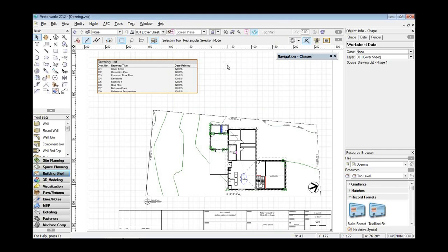That's why it's important to make sure that when you draw in Vectorworks, you're using the technology that's there, using wall styles. I've got some clients that like using unstyled walls, but they always have a problem when we get to the proposed drawings, because an unstyled wall limits your ability to make those changes, and it becomes quite laborious to make those changes afterwards.